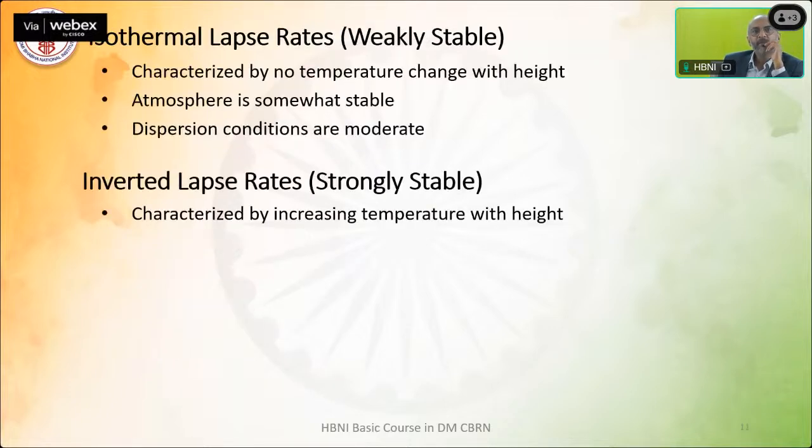And the isothermal lapse rate is weakly stable, characterized by no temperature change with height. Basically, there are not many changes, the atmosphere is somewhat stable, and dispersion conditions are moderate. And the inverted lapse rate is characterized by increasing temperature with height.